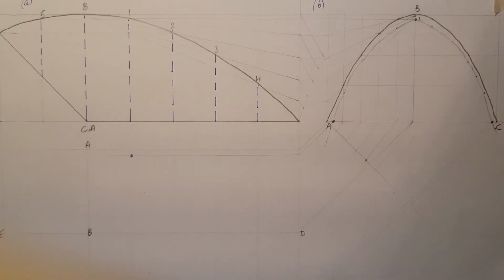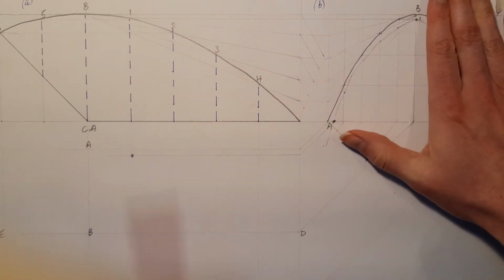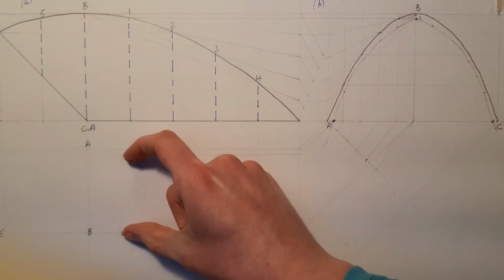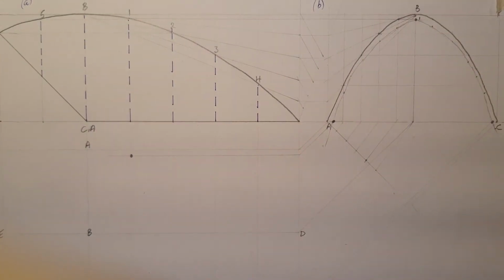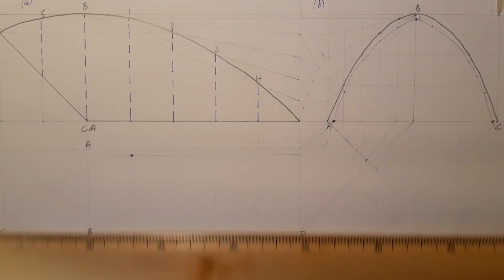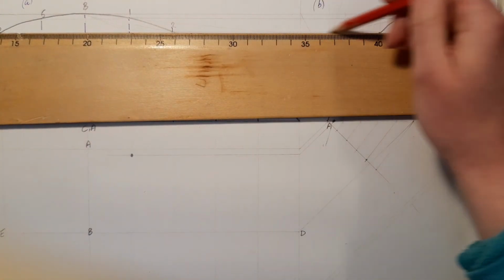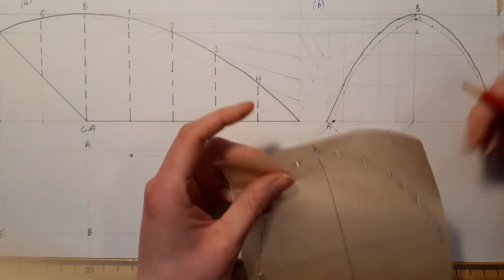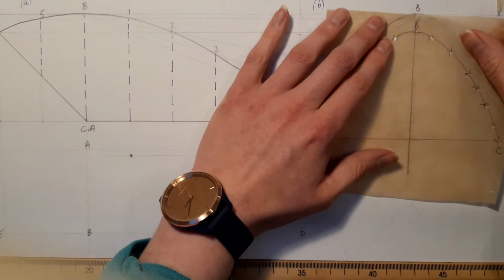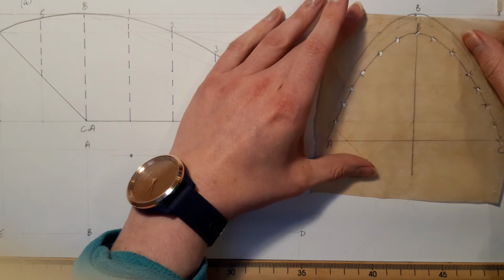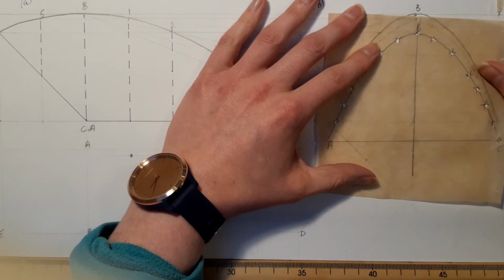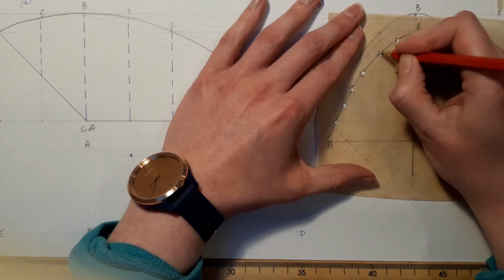Now, a lot of people actually only do 1/2 of the curve, so they only draw 1/2 of it. And what they do then is they transfer the height that they get over the other side, and it will make sure that it is perfectly symmetrical. So I'll show you that for the second one. Bring across the second height. Okay, so this is height number 2. Put B on 2, center on the center line, and this time I'm only going to do 1/2. Okay, and you can see the difference between both. So just do 1/2.